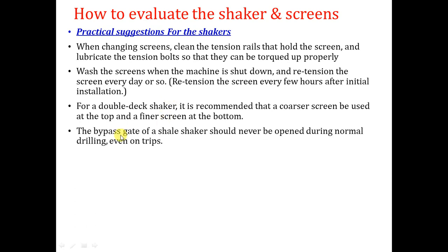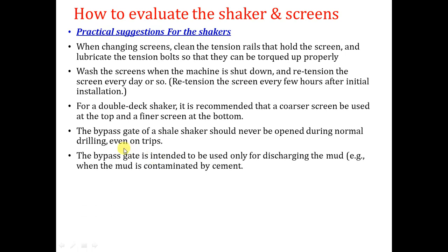Number four, the bypass gate of the shale shaker should never be opened during normal drilling, even in trips, but it is only used when cement is coming during the cement displacement, in order to send all the flow of the cement overboard, in order not to make a problem for the screens and for the shale shaker.